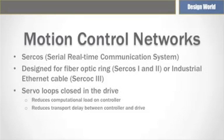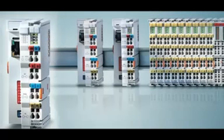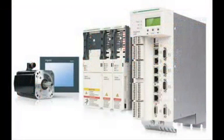Lastly is SERCOS, a digital bus that interconnects motion controls, drives, I/O, sensors, and actuators from numerically controlled machines and systems. It's designed for high-speed serial communication of standard closed-loop real-time data over a noise-immune fiber optic ring, SERCOS 1 and 2, or industrial Ethernet cable, SERCOS 3. In a SERCOS interface system, all servo loops are normally closed in the drive to reduce the computational load on the motion controller and synchronize more motion axes than it otherwise could.